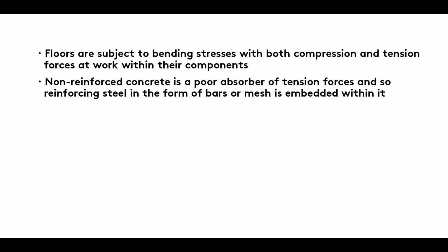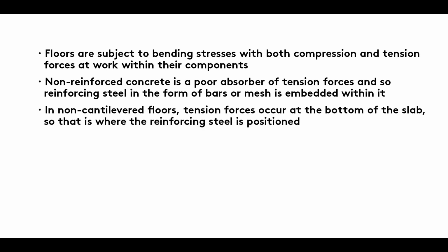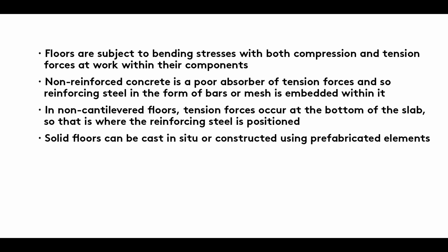Summary. Floors are subject to bending stresses with both compression and tension forces at work within their components. Non-reinforced concrete is a poor absorber of tension forces, and so reinforcing steel in the form of bars or mesh is embedded within it. In non-cantilevered floors, tension forces occur at the bottom of the slab, so that is where the reinforcing steel is positioned. Solid floors can be cast in situ or constructed using prefabricated elements.